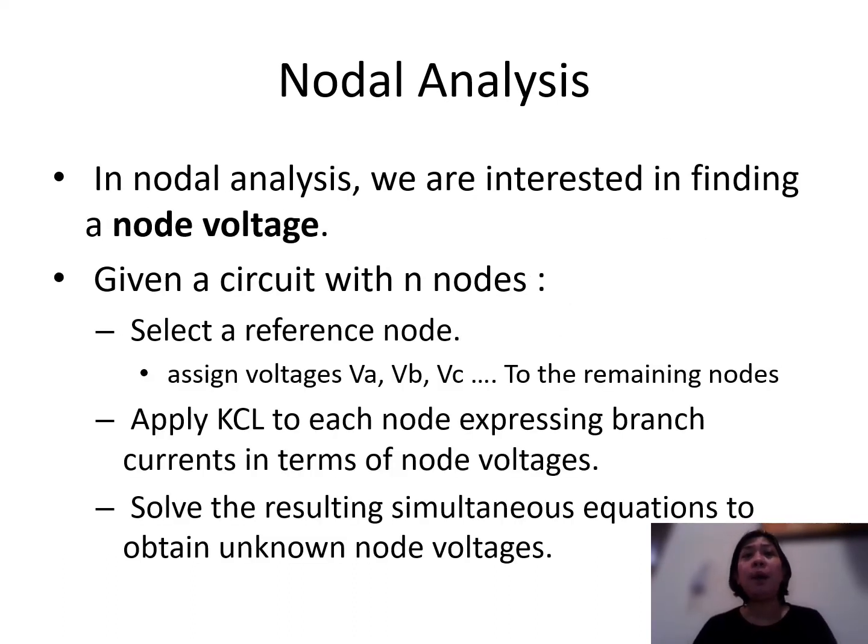In nodal analysis, we are interested in finding the node voltages. If in mesh analysis we were interested in solving for the mesh currents, this time we will be trying to solve for the node voltages. So this applies to circuits wherein your unknowns are the node voltages instead of currents.